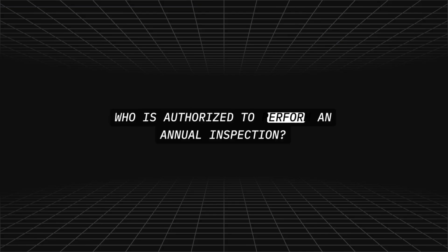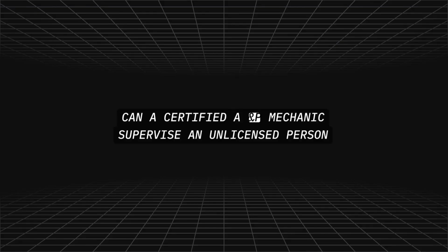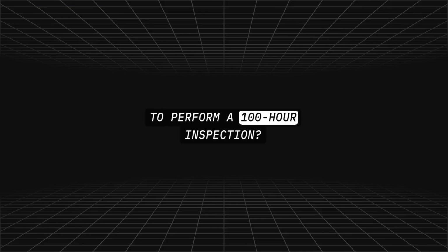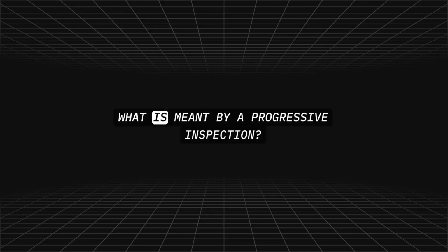Who is authorized to perform an annual inspection? An inspection authorization. Can a certified A&P mechanic supervise an unlicensed person to perform a 100-hour inspection? No. Only a certified A&P mechanic can perform a 100-hour inspection. What is meant by a progressive inspection?